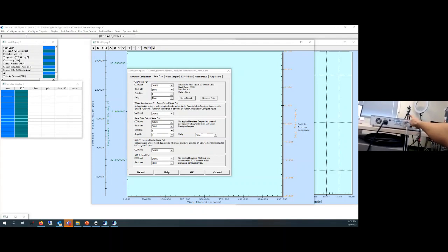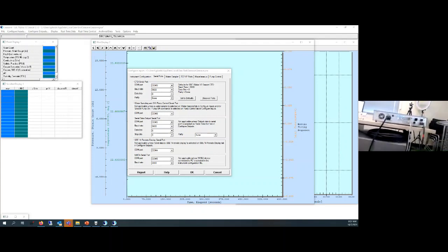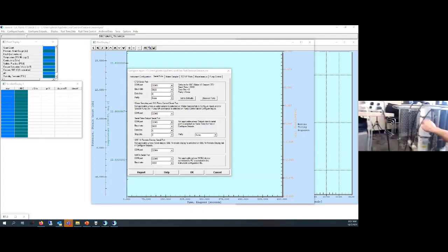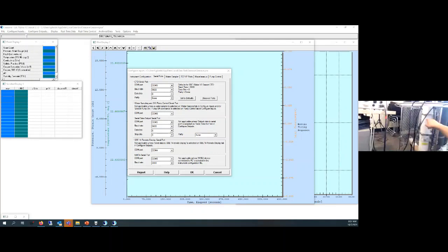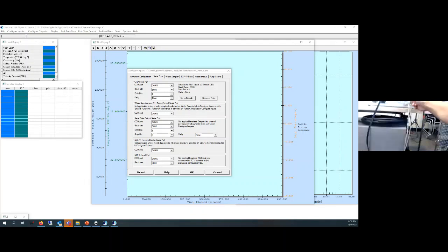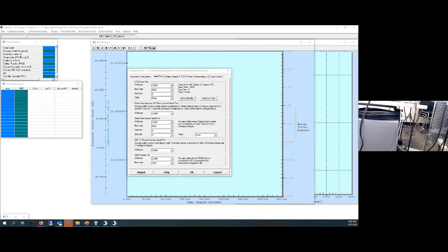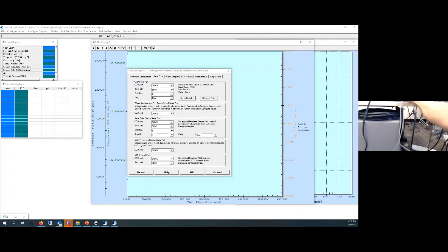This serial data connector is what we use to talk to the deck unit in order to talk to our CTD. So this is connected to COM9 at 9600 baud. This carousel data serial cable is what you use to get bottle confirmation messages coming from your SBE. You won't be able to send a bottle fire command from CSave because that travels through this carousel data connector to the 55, which sends a signal to trigger the latch assembly. So make sure that this is connected.